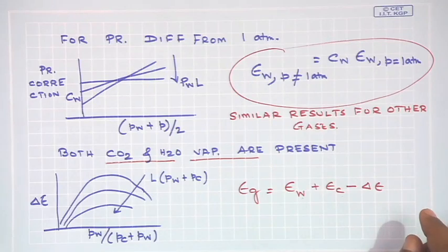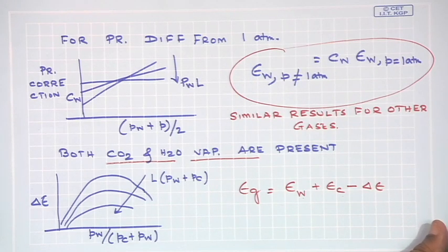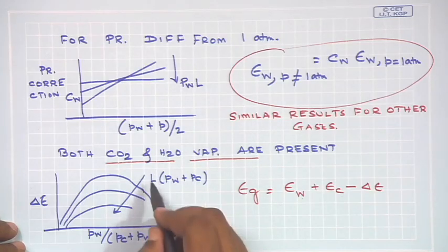So, the last thing remaining in our discussion is how do we get an idea of what is going to be L, the length scale. What is the length scale to be used, because you are not going to get a hemispherical mass of participating gas radiating with your surface of interest at the center. That is something which is very inconvenient to use and may not be the right calculation method.